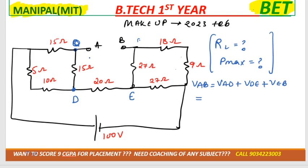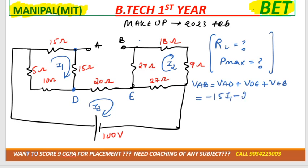Okay. If you are moving from A to D, current would also move from A to D. If you are moving from E to B, current would also move from E to B. If you are moving from D to E, current would also move from D to E. Now mark the sign and then tell me the equation. Okay, now cross check it. A to D, that would be minus 15I1. D to E, minus 20I3. E to B, minus 27I2. Okay.